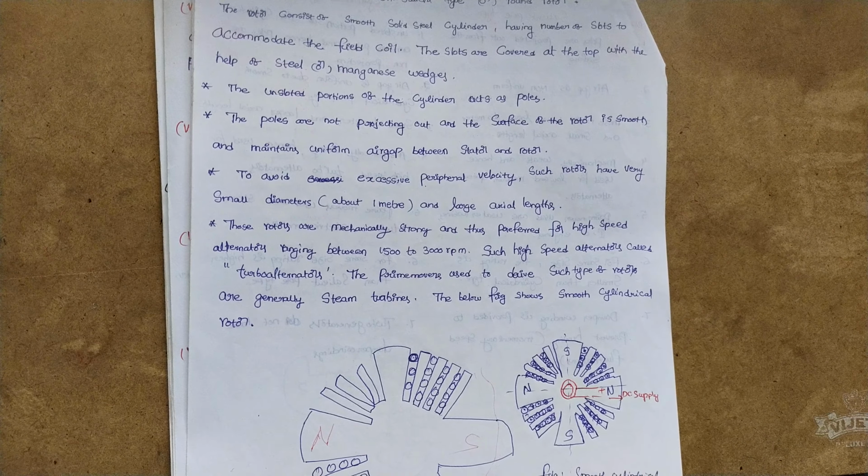If the coil span is less than 180 degrees, because the distance from north pole to south pole is 180 electrical degrees, but in short pitch winding the distance is not exactly equal to 180 degrees. The angle at which the coil span departs from 180 electrical degrees is called the chording angle.